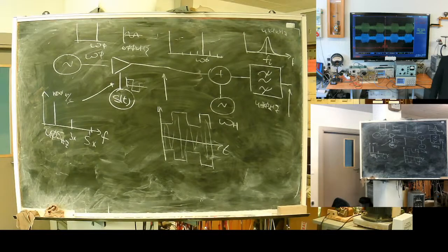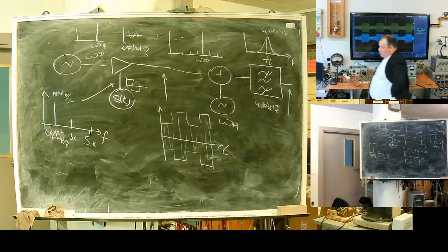a local signal source, mixer, and bandpass filter. I can transfer the full spectrum without change. If I would use a multiplier or a divider, the spectrum of the signal will be distorted, the spectrum will change. Here I have my signal transferred from one frequency to another without significant distortion. Its idea is behind the very popular technique of the superheterodyne receiver.